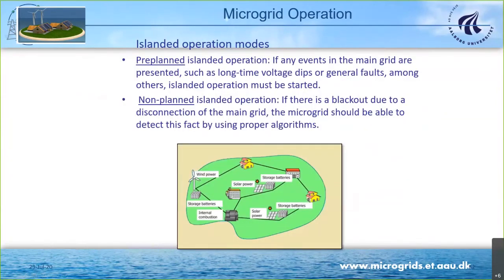Indeed, it's very dramatic when we have a grid connected system and without any plan, we just pass to island. Because if this system is just prepared to inject power to the grid, once it is not connected to the grid, then we may have problems of frequency and phase, and the system may work outside the acceptable frequency and voltage limits. So we have to start taking care of those two parameters.